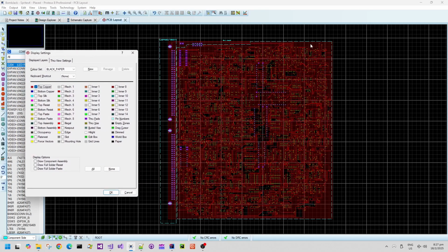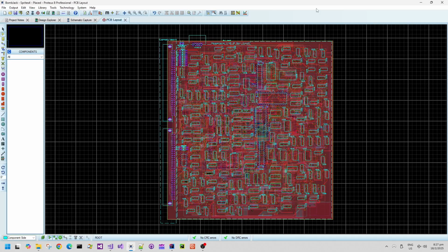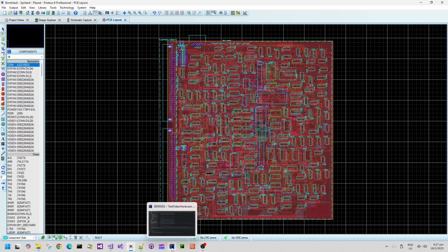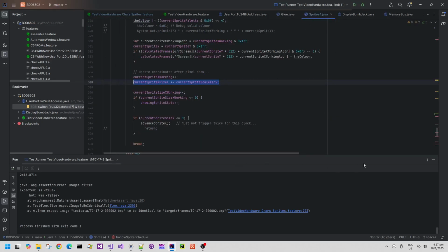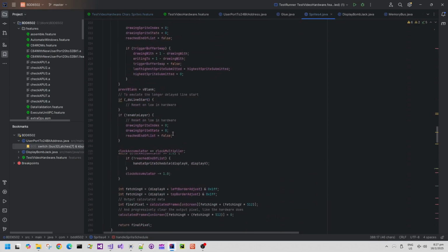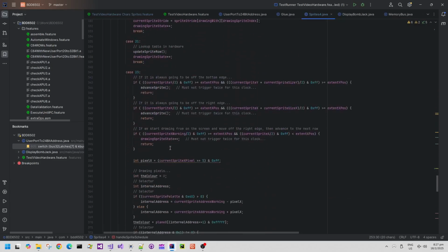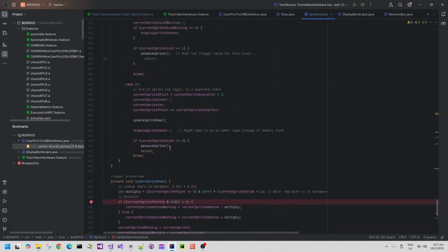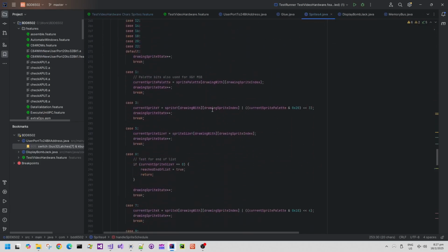Now I have to make some decisions on how many signal layers I'm really going to use, how many power plane layers I'm really going to use, and where those power plane layers are going to go to help signal integrity and all of that kind of stuff, and whether or not it's going to be better to make a board with more layers but smaller size, or larger size and fewer layers, because if you spread out the components, then you don't need so much signal density.